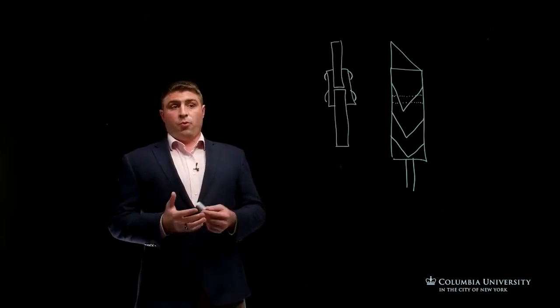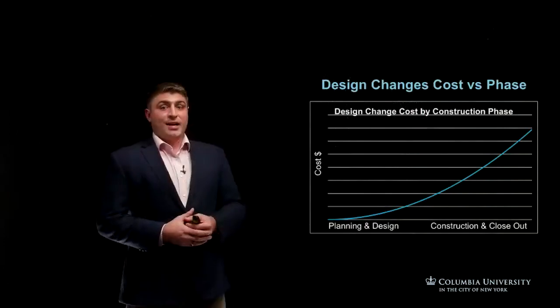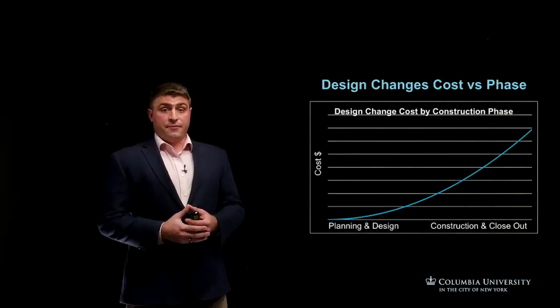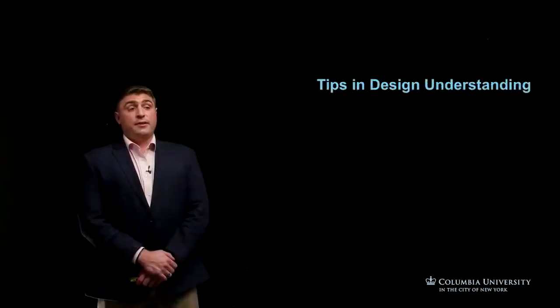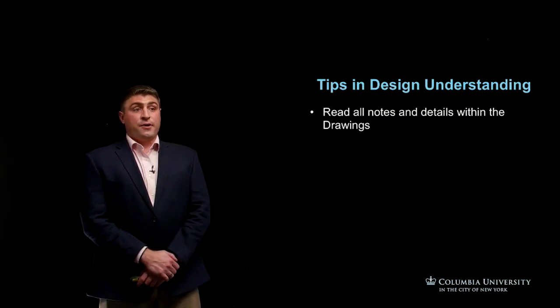I wanted to illustrate this point as it relates to design costs as the construction project continues. As you can see here, the cost of implementing design changes beyond the design phase can have significant cost impacts to your project. Finally, I'd like to offer you some tips in understanding construction design. It's very important that you read all the notes and details within the drawings. It's important that you generate RFIs or requests for information when the details are not clear. It's also very important that you maintain an RFI log so you can understand which items are open and which items need to be followed up with.